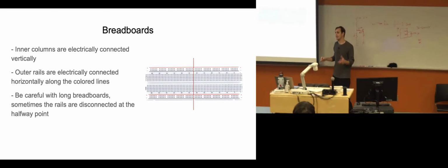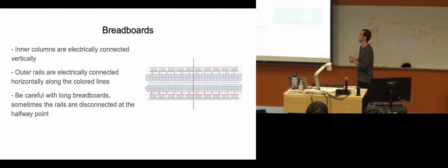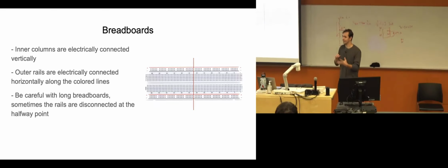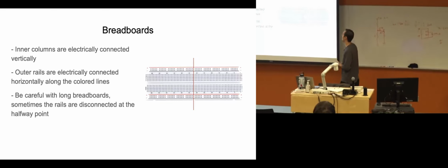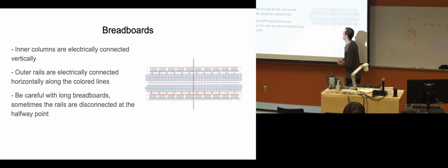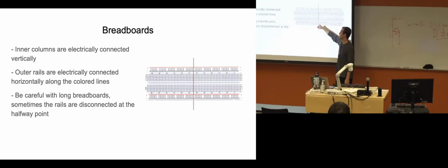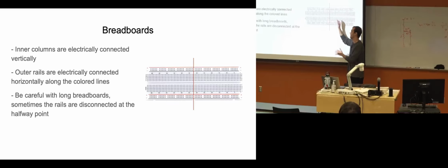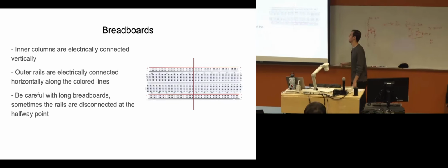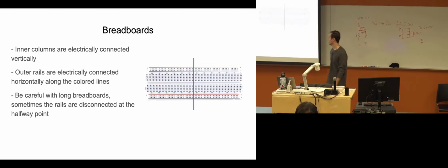It's a super common thing. I wired everything up correctly. I double-checked the circuit. It's not wrong, I promise. And the issue is just that it's not actually connected. So if you use these, either stick to one side or just put jumpers between this one and this one to make sure they're definitely connected. Yeah, just something to be aware of.